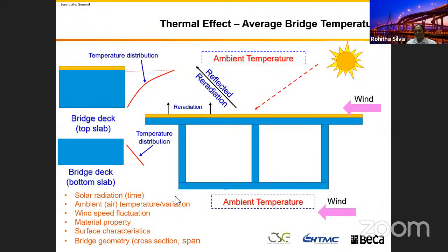If you design a continuous span bridge, this significantly affects it, because you see there is no uniformly distributed temperature in here. If you know temperature is proportional to strain, and the temperature distribution is like that, then your strain distribution within that cross section represents exactly the same.